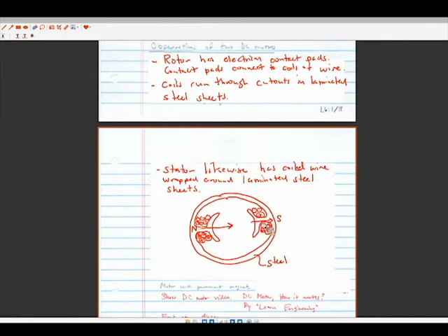We haven't gotten to what the rotor is going to be, but the rotor is going to fill this space in between. It's going to make very small air gaps between here and here, because we're going to have something magnetic or ferrous connecting all this. This structure is called a salient pole.